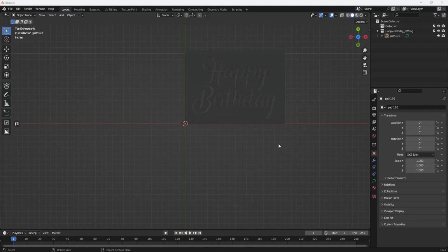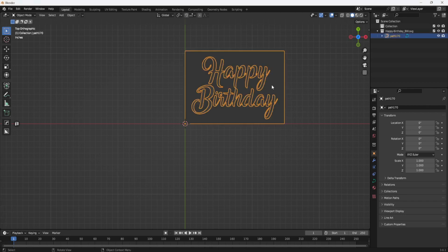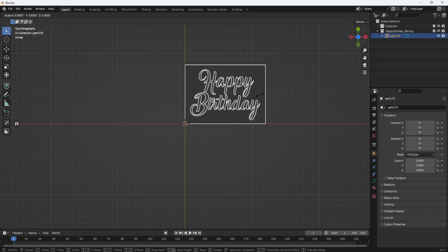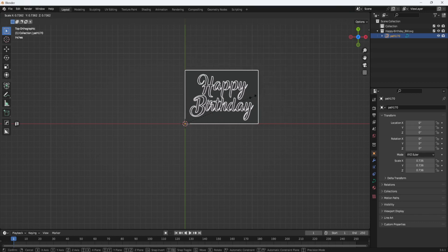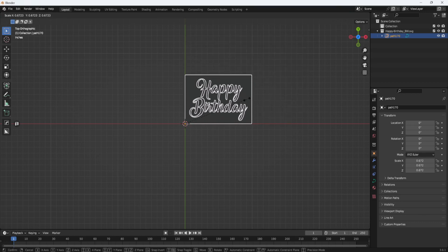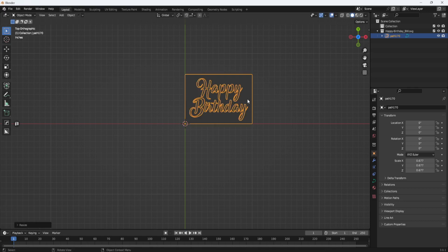It's a little big, so I'm going to resize it slightly. Click on the graphic to select it, then hit S and drag your mouse to increase or decrease the size. I'm going to drag mine down and make it about 12 inches long on the X-axis using my grid lines for reference, and then left click to stop scaling.